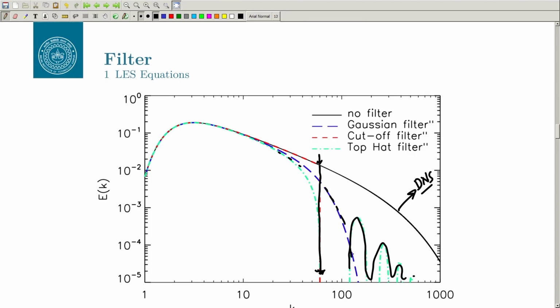And this is what we have been discussing when we are talking about LES, that when you have this E(k) versus k, okay, you are not resolving everything, but you are cutting off at a certain point, and as long as you ensure that it is capturing 80% of the energy, this region does not matter, because this is primarily responsible for the dissipation of energy, which does not participate in the key dynamics of the flow. Okay.